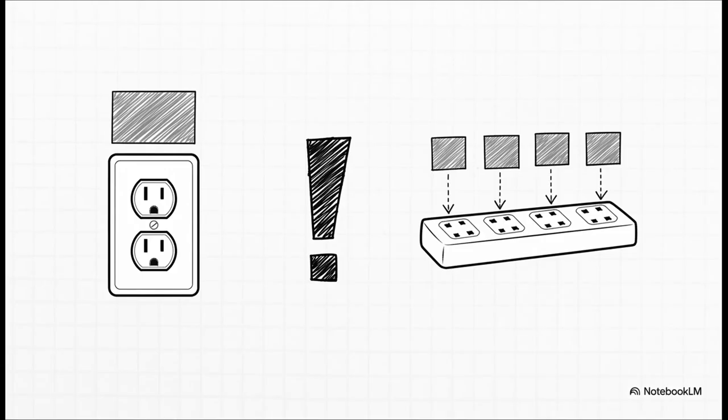So here's the deal. Under 220.14(I), each standard receptacle point, and that means a single outlet or even a duplex outlet on a single yoke, gets calculated at a minimum of 180 VA. But there's a big exception here. If you have a single piece of gear with 4 or more receptacles on it, like a power strip, the calculation changes. It becomes 90 VA per receptacle. That's a huge difference, so remember that one.